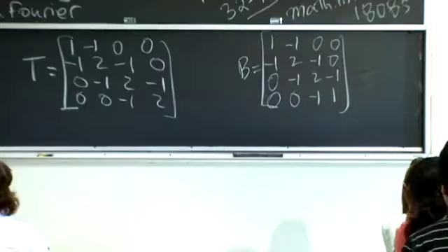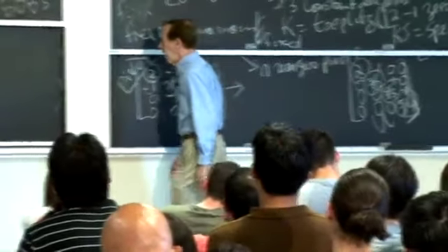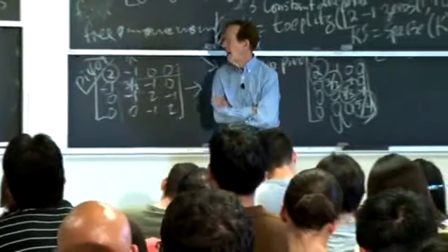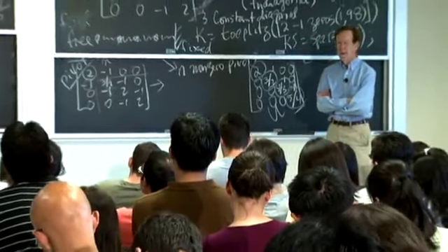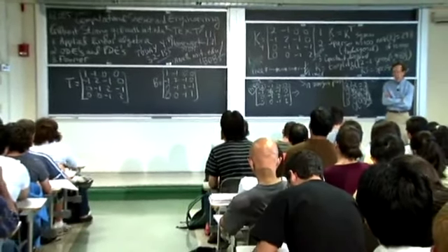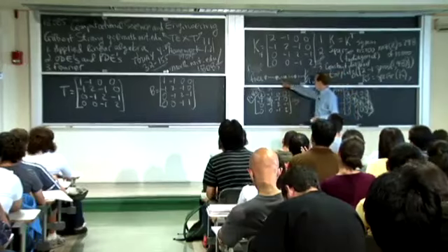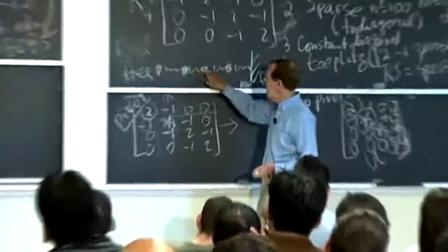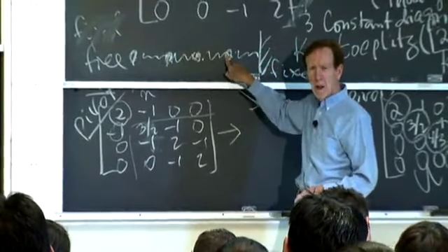Now, what do you think? So, we've drawn the free-fixed one. And what's your guess? They're all symmetric. That's no accident. They're all tridiagonal. No accident again. Why are they tridiagonal? Physically, they're tridiagonal because that mass is only connected to its 2 neighbors. It's not connected to that mass.